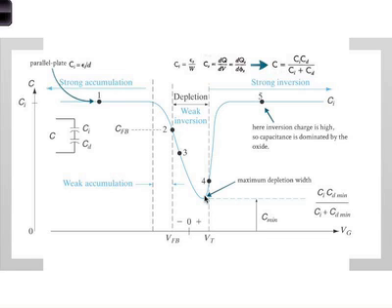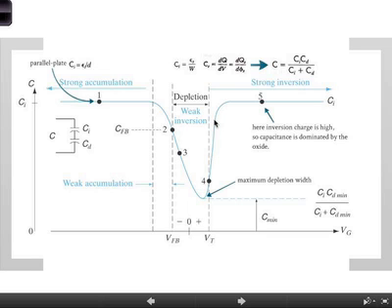Okay? When inversion happens, although you have a depletion region, very close to the interface you have majority carriers because it has become N-type. And there are electrons. So now, this capacitance starts going up again because you're getting contributions from the majority carriers, which can respond really fast. But now the majority carriers are electrons. Okay? So that's what's special about this. So this capacitance starts going up again.